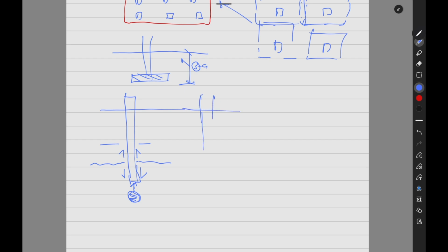They are like this. They might not go into the bedrock level, but they rest on very hard layers. So you have adequate friction here, and the end bearing. These are the two parameters we consider for the foundations. This is skin friction, and then this is end bearing. These are the two things that we use for the design.